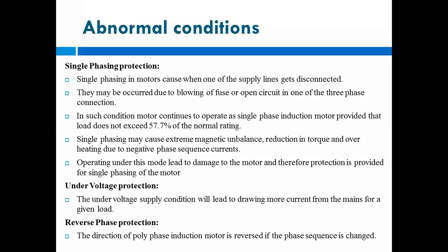Okay, now it may occur due to blowing of a fuse or open circuit in one of the three phase connections. If your fuse blows, it will also disconnect the supply, or if any one of the phases gets open circuited, due to that also this single phasing occurs.